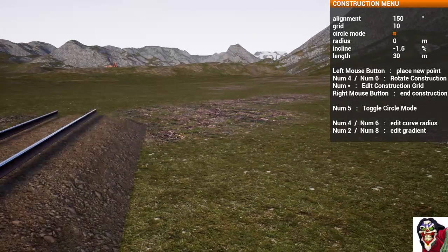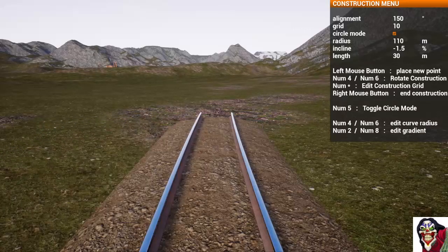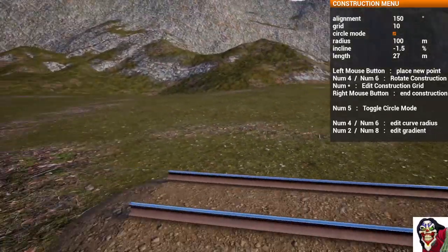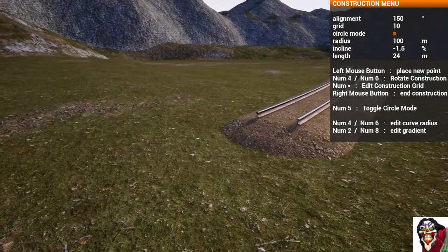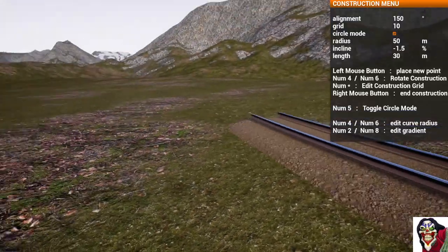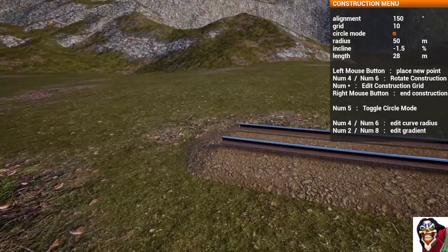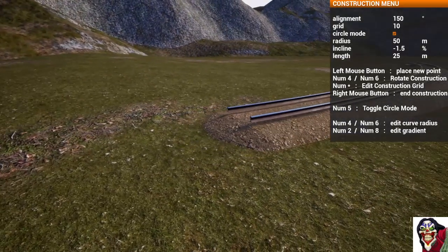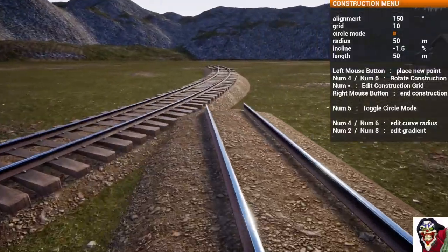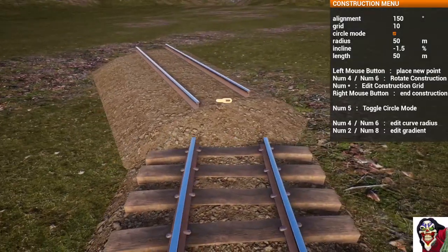So let's start curving the track around. About 100 meters, I think we've got to go a little bit tighter than 100 meters. Let's make it 50, which will point us over there towards that little ridge. So we want the transition piece to be 25 meters long. And click it in. And that's gotten us from level, and now this end here is pointed down at 1.5.